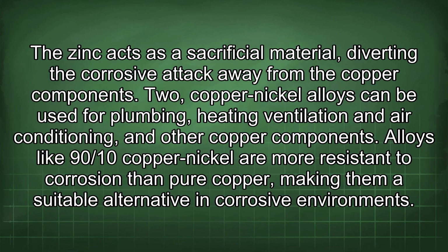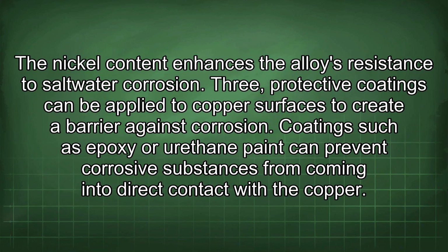2. Copper-nickel alloys can be used for plumbing, heating, ventilation, and air conditioning, and other copper components. Alloys like 90/10 copper-nickel are more resistant to corrosion than pure copper, making them a suitable alternative in corrosive environments. The nickel content enhances the alloy's resistance to saltwater corrosion.